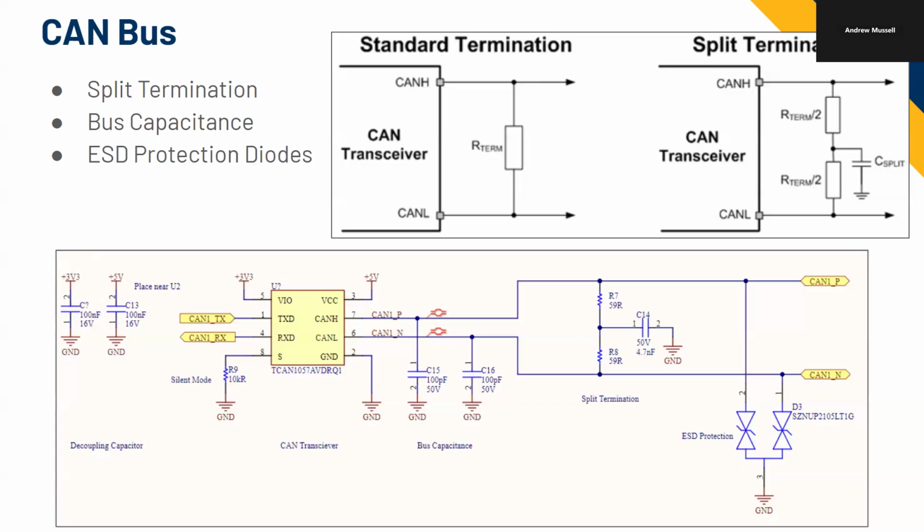I added these capacitors onto the CAN bus lines on each node. They don't have to be populated, but doing things like this in your circuit design is good, like putting pads for components that you may or may not use.